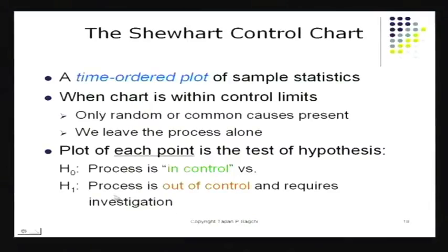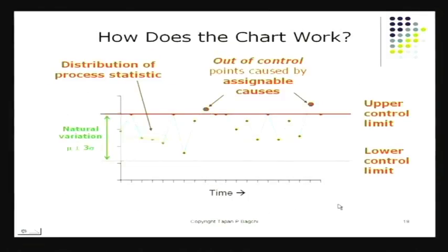I've got something called the process is in control, which is the base case, and the exceptional case is the process is out of control. These two I figured out by looking at the actual chart itself. So here's an example. I plotted the chart. I've plotted here, for example, the XBar value. When I plotted the XBar value here, and I've got the plotting done for various samples that have come along, I notice the upper and lower control limits.